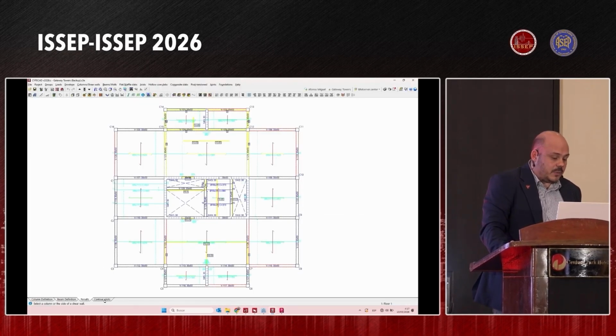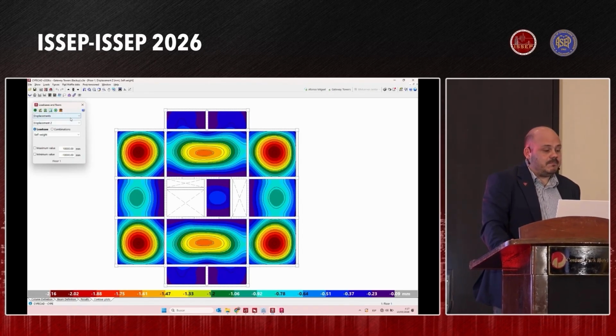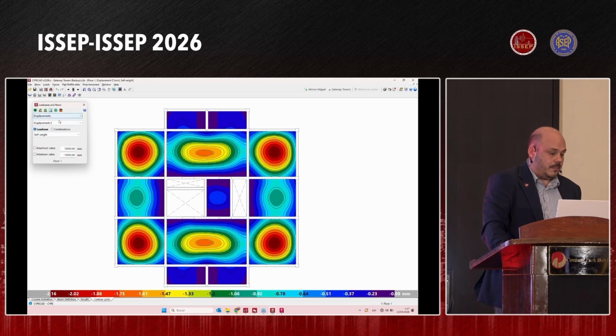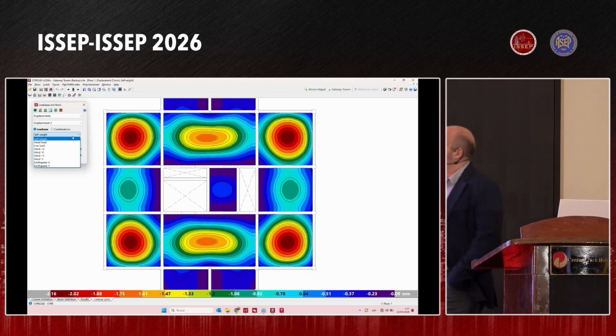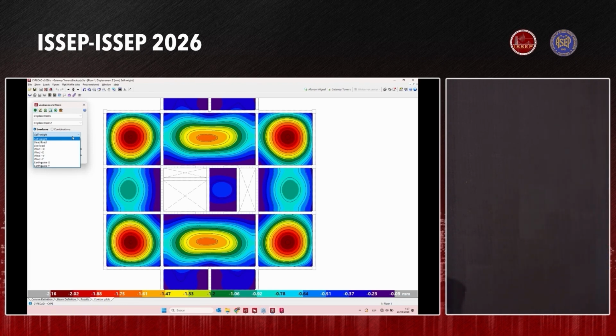Here in this project, we can also see, for example, if we talk about the slabs, contour plots showing us different information that is related to the load cases that we have in the project. For example, the different displacements, rotations, okay, for different directions here. Also, forces of the project, design forces, ratios. So this is information from the analysis. But again, very, very integrated in the BIM model. And when we have different load cases, we can see even these results for the different load cases or different combinations when that is the case, okay?